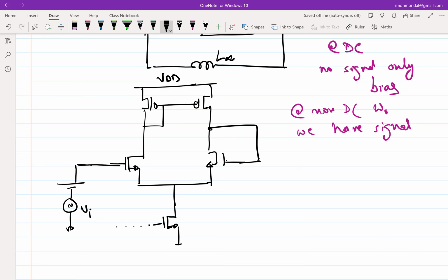Okay, so what is the feedback? Where is the feedback getting set? Your feedback is getting set through the drain of M2. So I can break it here. So this is L infinity. And if I call this V0, whatever V0 over Vi is will be your open loop gain. Correct? This is under unity gain feedback.